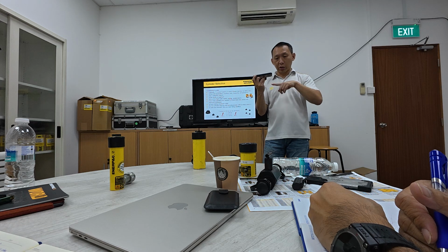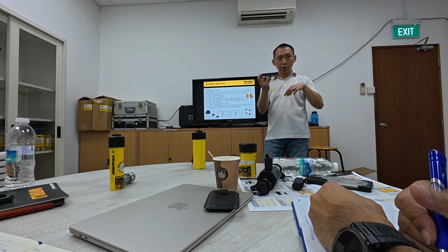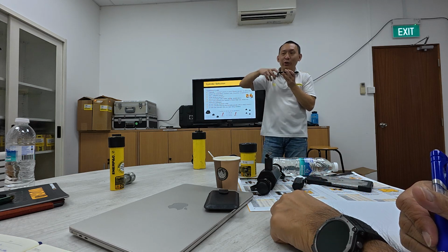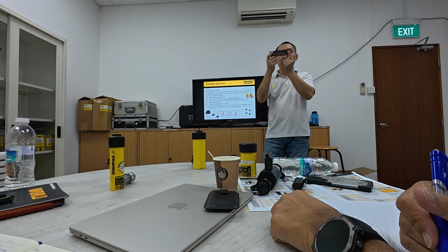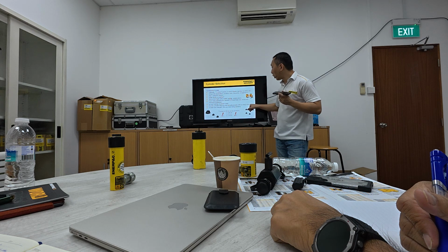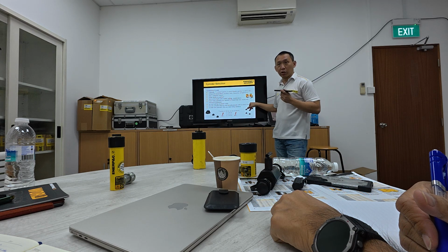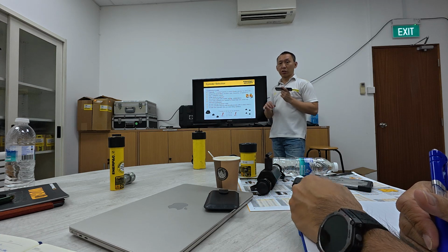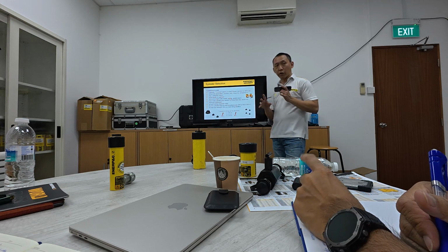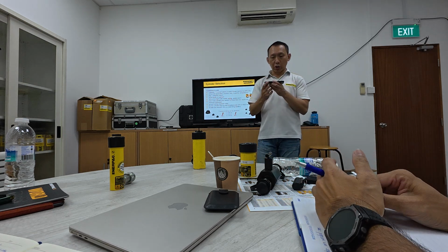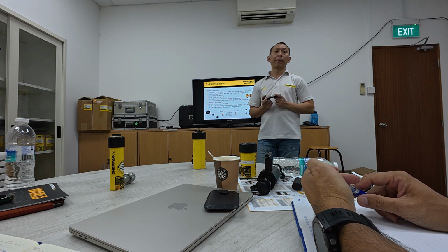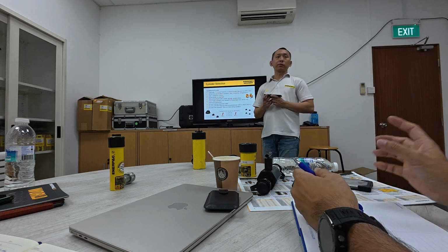What you can do is have a flow control valve at each point, and the one that's fastest, you close it like a tap, lower, smaller flow, so that it will be evenly lifted. We have this flow control valve inbuilt in the manifold, the A31, A41. This is one inlet, two outlets. This is one inlet, 4 outlets. So this is how you control lifting with the flow control valve. The maximum is 1 inlet and 4 outlets,